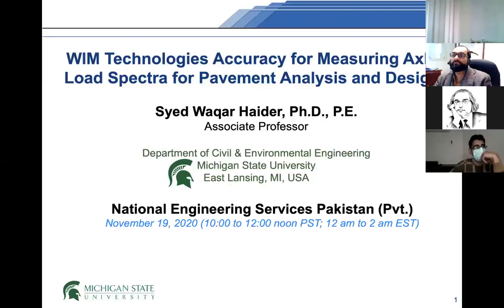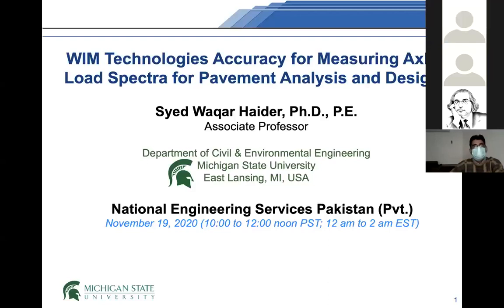As most of you in civil engineering probably know, in the US we still use AASHTO 93 design. We use ESALs. But now we are transitioning to the mechanistic-empirical design, the new AASHTO called Pavement ME, in which we don't use ESALs, we use load spectra. So the importance of WIM technology is even more now, as we need more accurate axle load spectra for our pavement design.